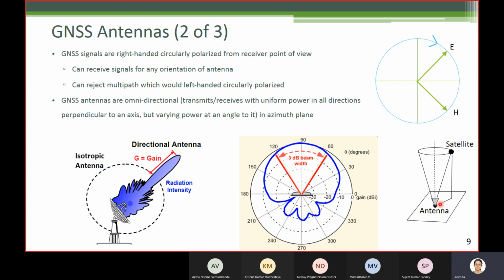Okay. Now you choose some reference direction on the antenna horizontal plane. Just like this vertical axis, just pick some reference direction with respect to the antenna horizontal plane. Okay. Now this line makes an angle with that reference line on the horizontal plane. That angle is called azimuth.